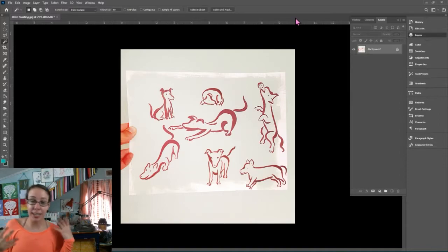This is the actual size that would be a good size to work at. And remember, in Photoshop, you really should have the size you're going to work at ahead of time. When you start the project, you want to know what size you're going to work at. So I am going to work at 300 pixels per inch, and this is as many pixels as my image can handle. But if I raise the size to 300 pixels per inch and then I traced over one of these or whatever, I wouldn't be able to necessarily make it bigger. So make sure that things are the right size.